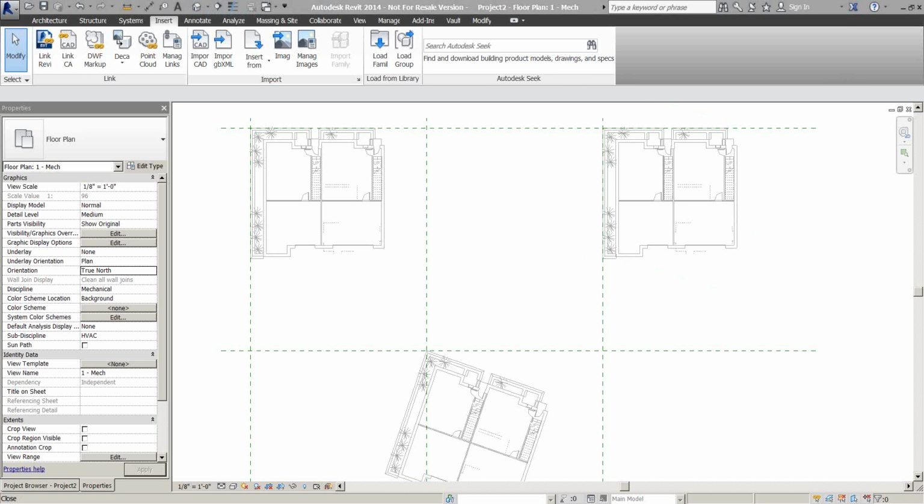But if you're looking for the actual building itself, that will be changed. So it depends. Are you moving the overall building up in elevation, or just a level inside? This has to do with the elevation of the overall linked model, not necessarily the levels inside the model. So no, you wouldn't have to re-record if you're just changing 12-foot plates.